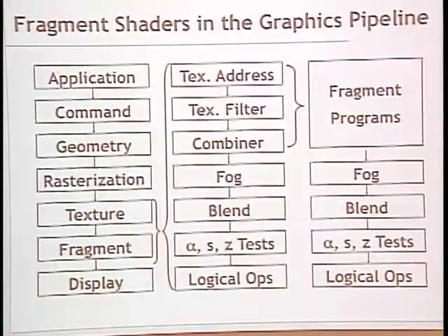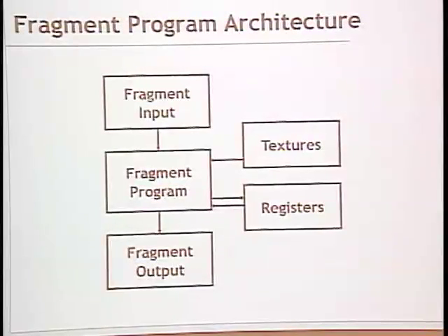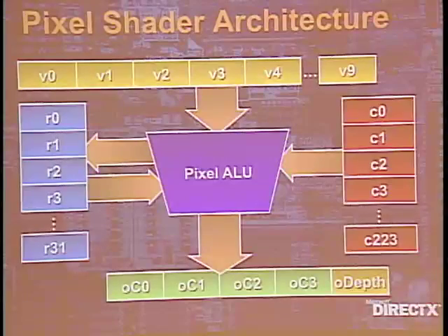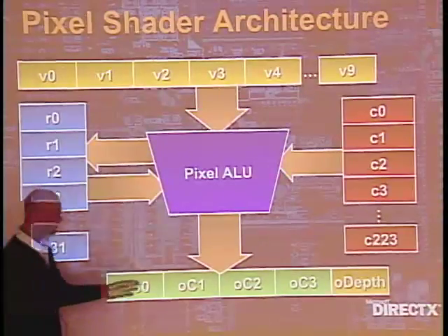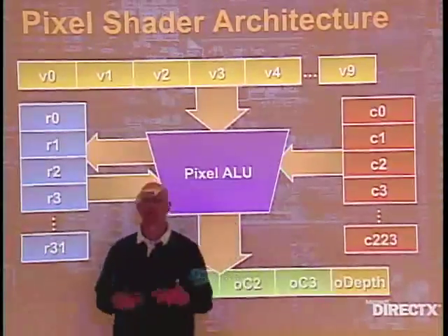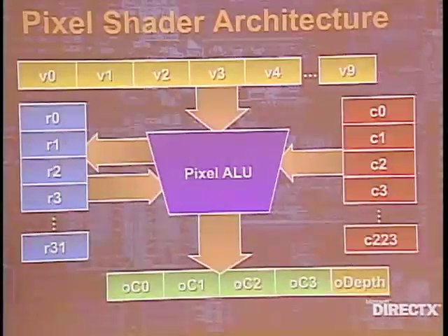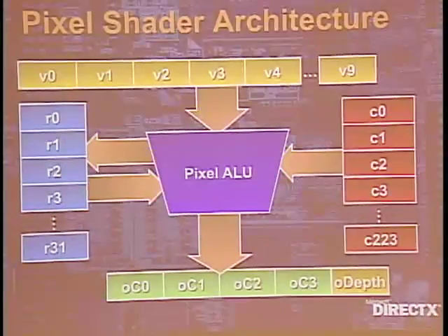So the big difference between the fragment program, at least the original fragment program, and the original vertex program is the fragment processor needed to go out and talk to texture. Other than that, they look very similar. So we look at this picture here. It looks pretty much the same. Okay? Doesn't have constant registers, does have textures. Okay? Here's Microsoft's really groovy picture. Right? What does that look like? Pretty much the same thing, although they're completely missing the textures. Good job, guys. Okay. What we do have here is the color, the output color. We also have to somehow compute the output depth, how far away that is. Okay? Basically, this is the same picture, though.